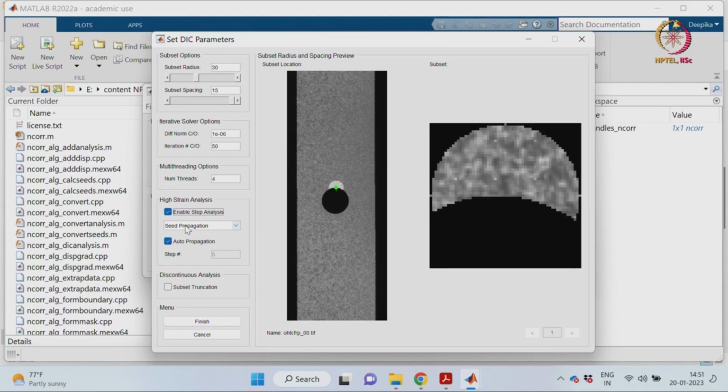But let us say we do not want to do this and we want to manually select that after every fifth image the reference image should be updated. So, we can select this leapfrog option and give the step when we want to update our reference image. Let us say I am just assigning 2, which means every third image will have a new reference image.